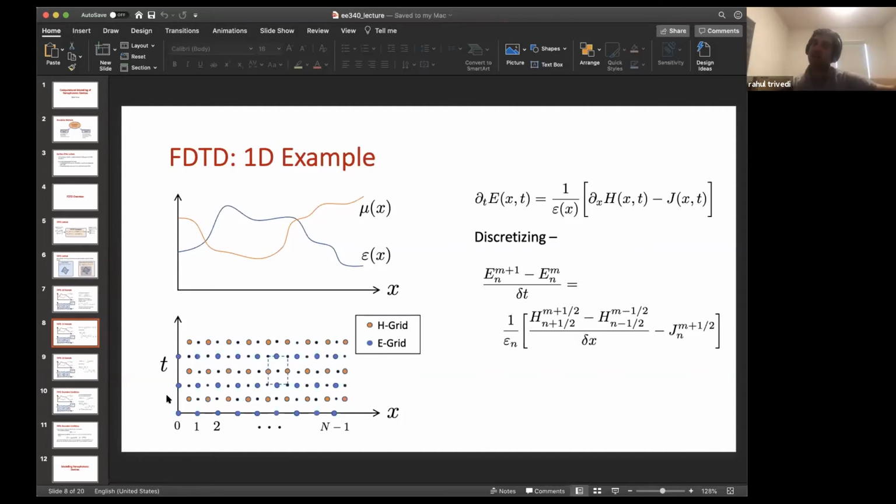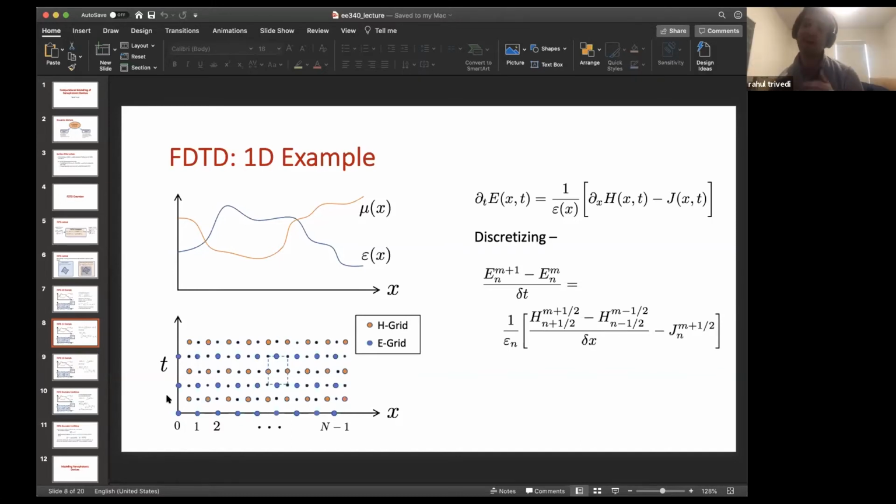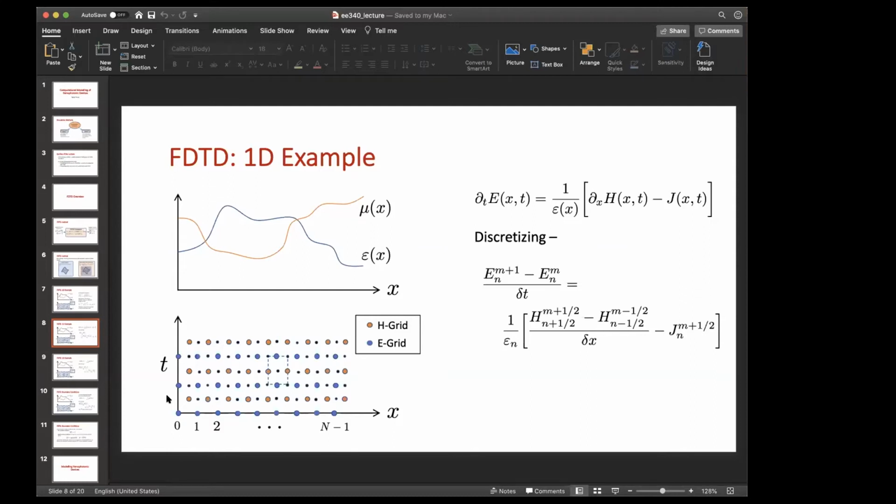But if you start using derivative information that requires a lot of data, then that parallelization starts becoming more complicated. So there is a trade-off there. It's an accuracy versus speed trade-off, but higher order derivatives have been used. These higher order FDTD methods have been used in harder problems with varying amounts of success in the computational EM community.